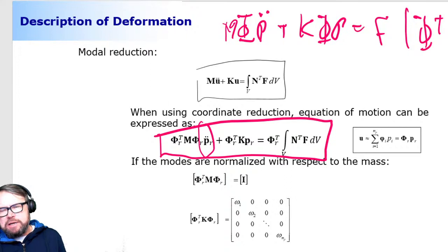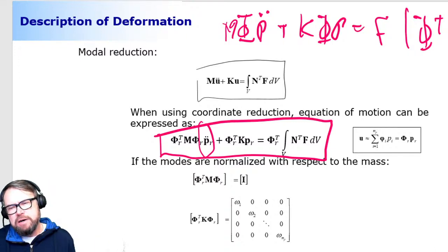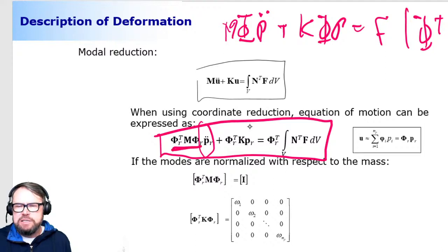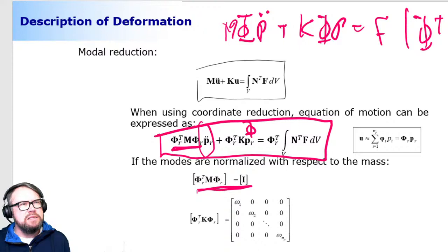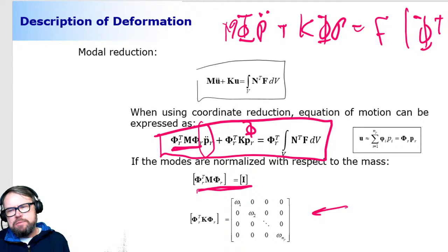And because the modes, well, depending how they are selected, but if the modes are orthogonal, like they always are if you are conducting an eigenvalue analysis, it means that the new inertia, oh, this is, by the way, missing this guy here, a new stiffness will have a diagonal representation, meaning that these modal coordinates have no relation to each other. So you can just take one modal coordinate and solve that, knowing nothing about other modal coordinates. And this is very different from the original finite element modeling, because in original finite element modeling, the mass and stiffness are not diagonal, but they are block diagonal representation, meaning that you cannot just solve one degree of freedom knowing nothing about other degrees of freedom. This is a great advantage, which we're going to discuss a bit more next week, Wednesday.